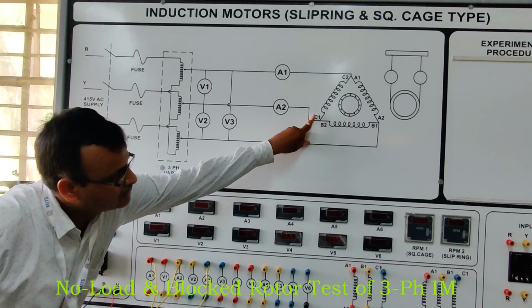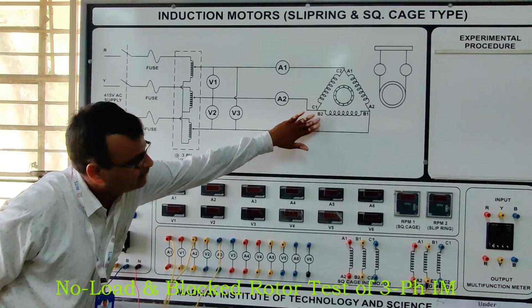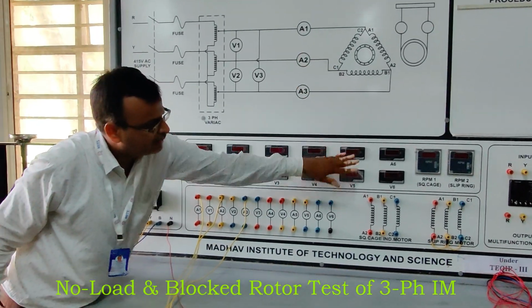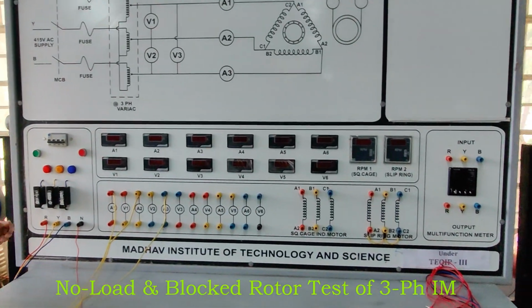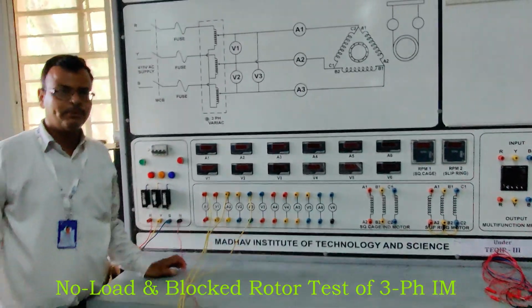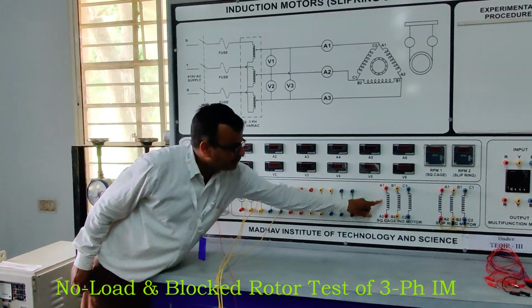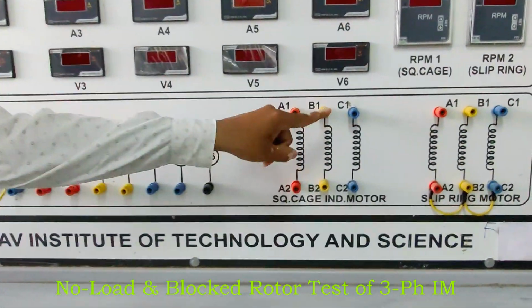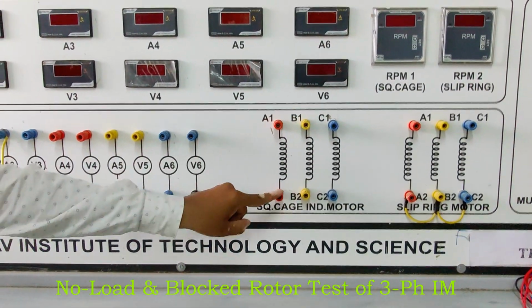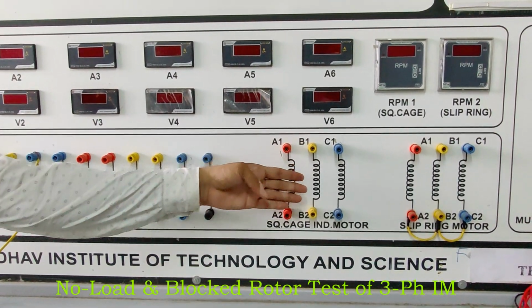This is the squirrel cage induction motor connected in star connection. We will connect the star connection. You may also connect delta, but we will connect the star connection. How to connect the star connection? You know, in a star, similar points are connected, either the starting or the finishing ends. See that these are the 6 terminals, A1, A2, B1, B2, C1, C2. Depending upon the connections, you may connect in star or delta.